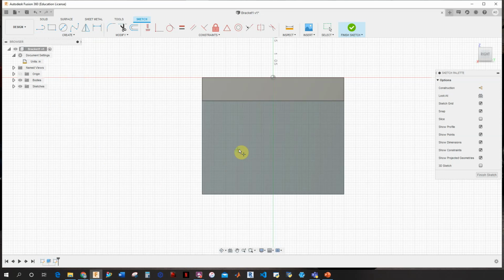So what this is going to do is just create points in that sketch. I'm setting or defining the locations that I'm going to later use for the hole tool. Now the points here are not defined, so they're just sitting in that plane for that sketch. But I actually need to define the distances for those points. That way I can set everything correctly.